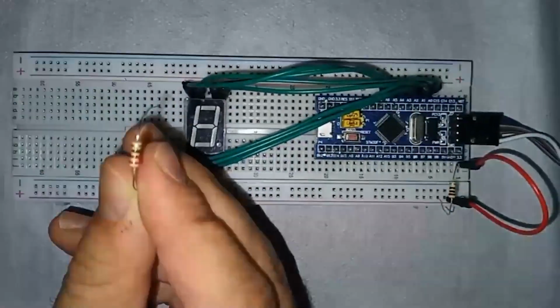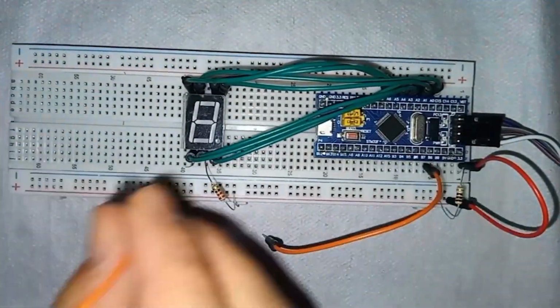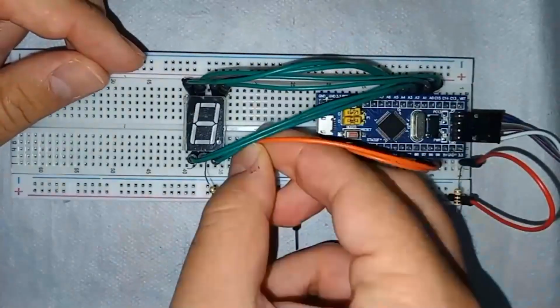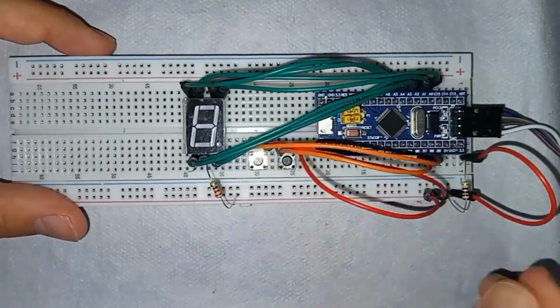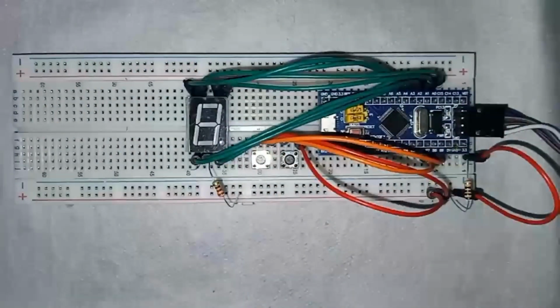By using decent resistors and connecting two push buttons to pins B6 and B7, your final circuit should look something like this. In fact, I've corrected the circuit. I've connected the common pin of the 7 segment to 3.3 volts via the 330 ohm resistor,